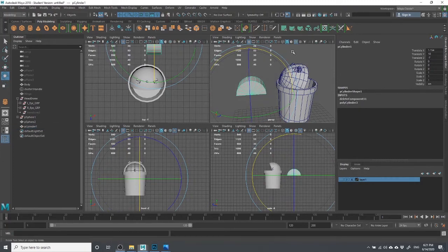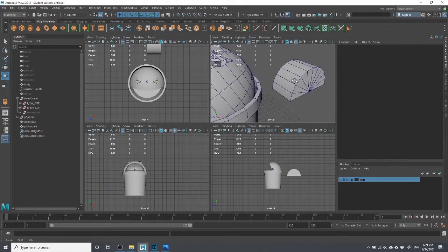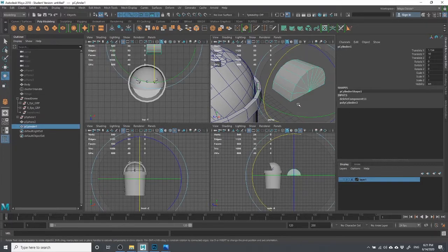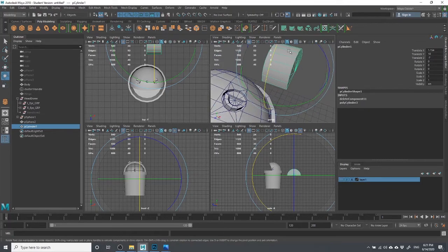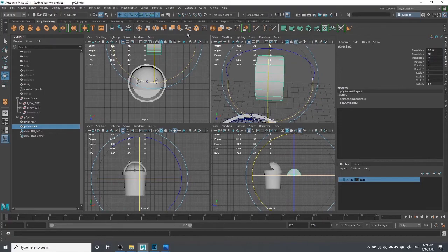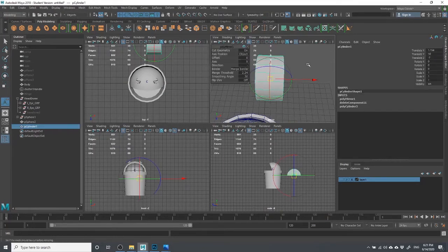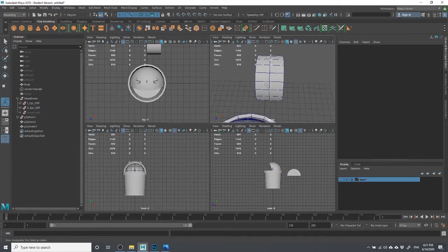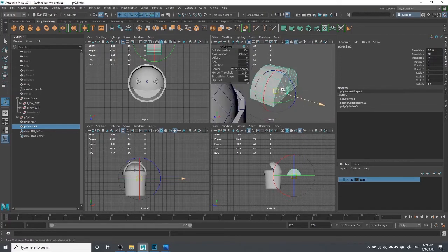All right. So I have this cylinder here for part of the arm, like I was saying. Well, check this out. Here's what we can do. If I had thought this through a little bit, what I could have done is just put a division down the middle. But because we don't have that, here's a little hack that I'm going to do. I'm simply just going to mirror this, and that achieves the same effect. I've just now got a cut straight down the middle of this half a cylinder, and that's pretty much what I wanted.